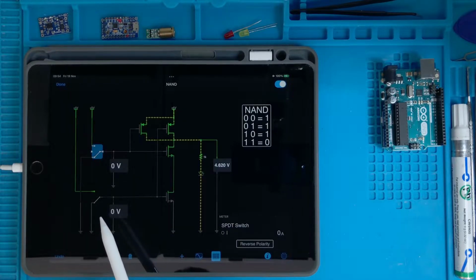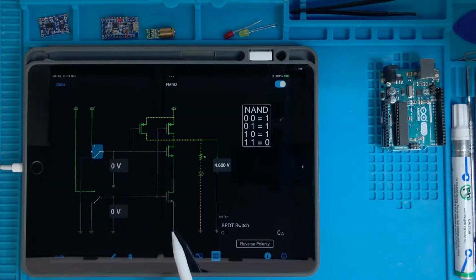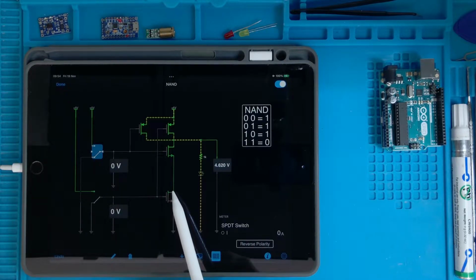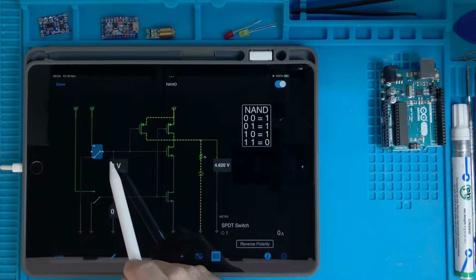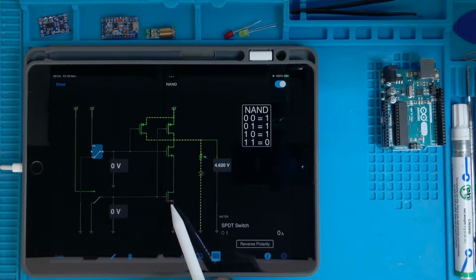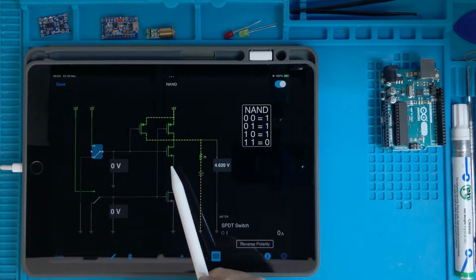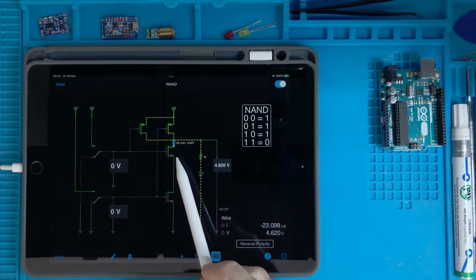Specifically, the first gate connects this to 0, and then the VDS of this transistor becomes 0, and therefore if the source is 0, also the drain is at 0, and therefore if I put the gate of this transistor to 0, it is 0 with respect also to this point, which is 0 because this transistor has a VDS which is 0, and therefore also this one makes its own VDS to be 0,